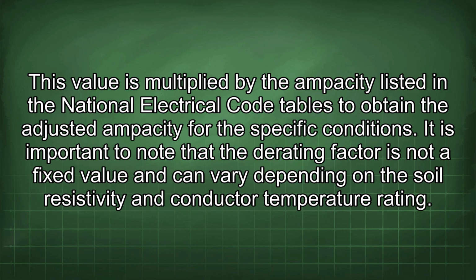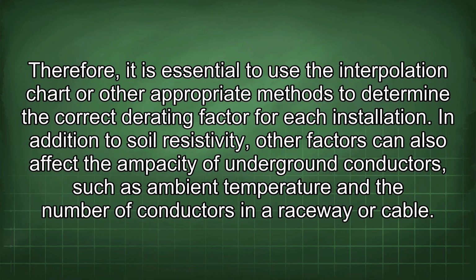This value is multiplied by the ampacity listed in the National Electrical Code tables to obtain the adjusted ampacity for the specific conditions. It is important to note that the derating factor is not a fixed value and can vary depending on the soil resistivity and conductor temperature rating. Therefore, it is essential to use the interpolation chart or other appropriate methods to determine the correct derating factor for